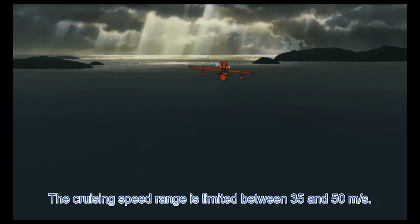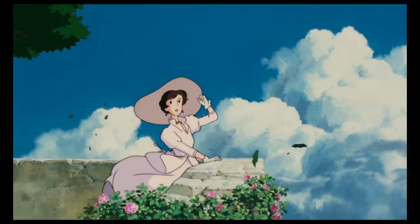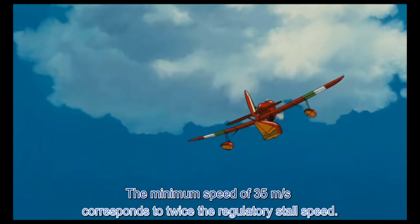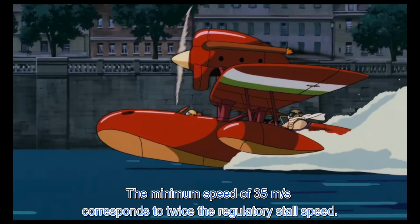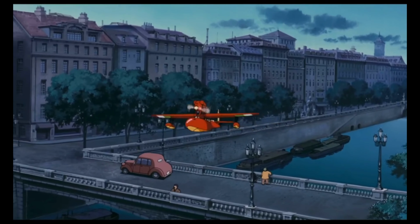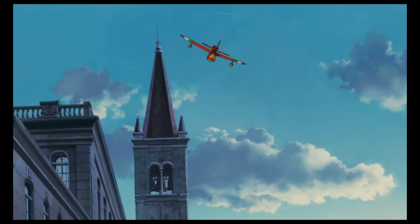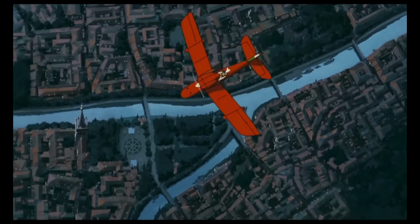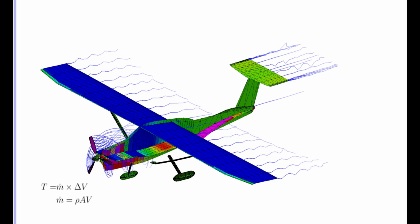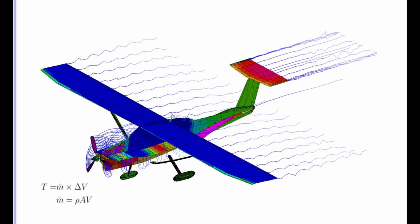The minimum cruise speed is set to 35 meters per second, which is approximately twice the stall speed of 18 meters per second specified for a Class 3 aircraft. This ensures sufficient safety margin, while also avoiding excessive induced drag that would occur at lower speeds. Here, the thrust is calculated from the difference between the velocity behind the propeller and the velocity in front of it, which is the flight speed.